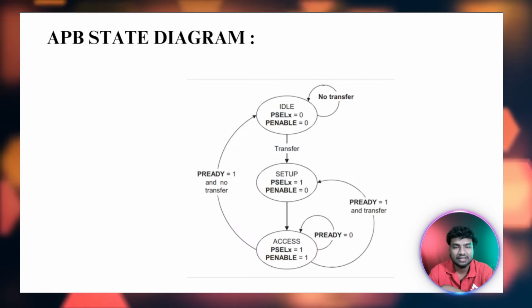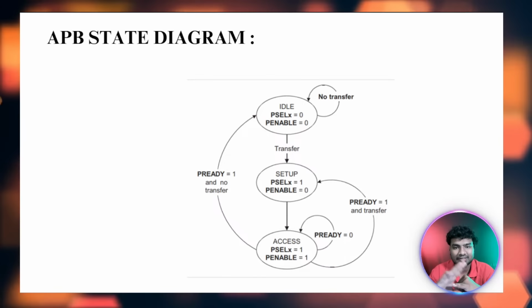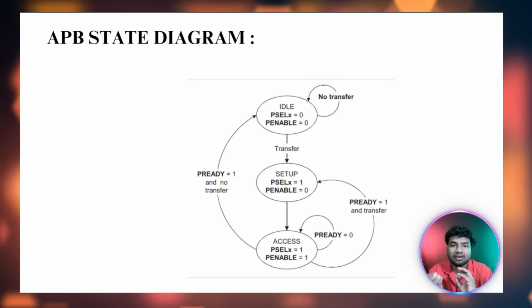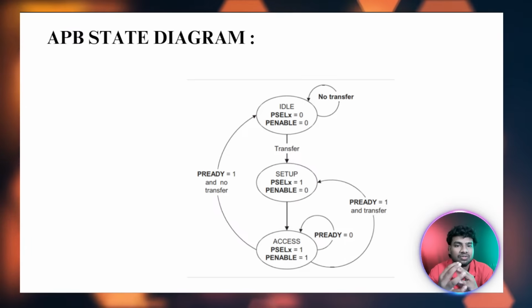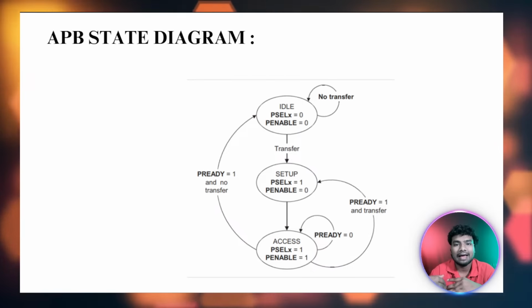In the access state, the actual data transfer will happen. If both PSEL and PENABLE are high, the master can send or receive the data. So the master can make the transfer in the access state.